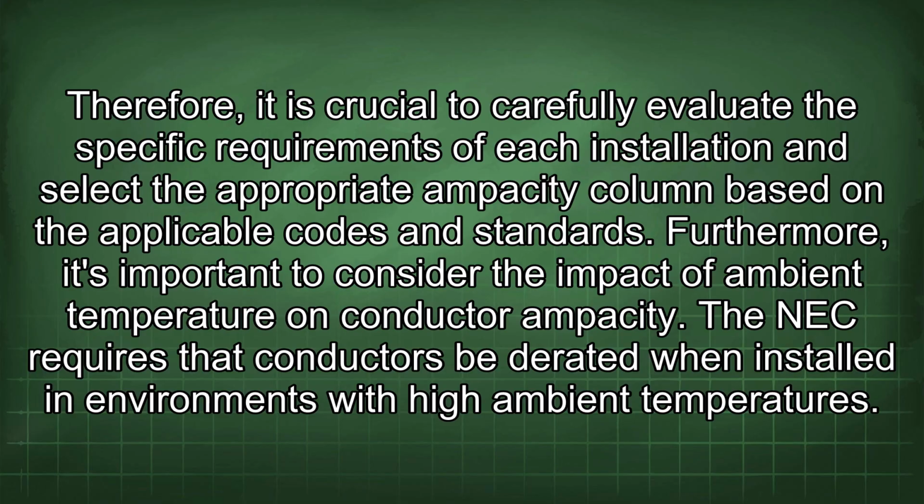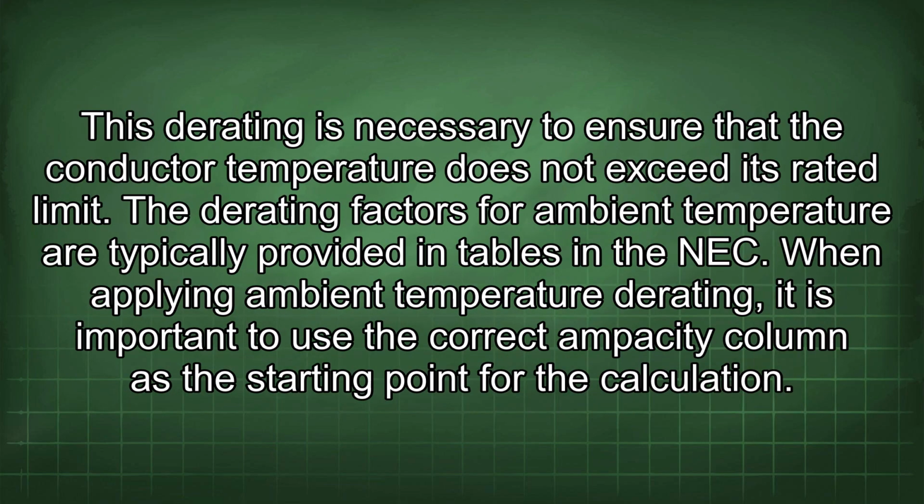Furthermore, it's important to consider the impact of ambient temperature on conductor ampacity. The NEC requires that conductors be derated when installed in environments with high ambient temperatures. This derating is necessary to ensure that the conductor temperature does not exceed its rated limit. The derating factors for ambient temperature are typically provided in tables in the NEC.